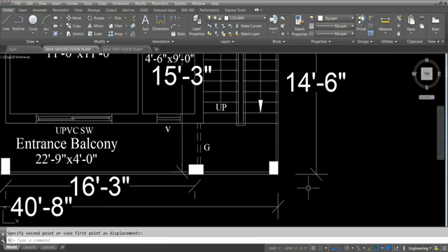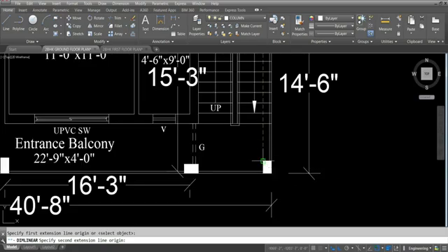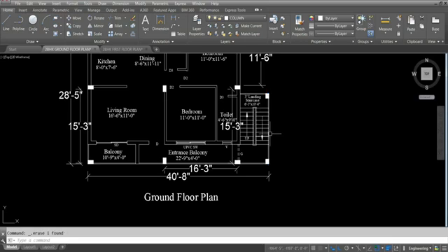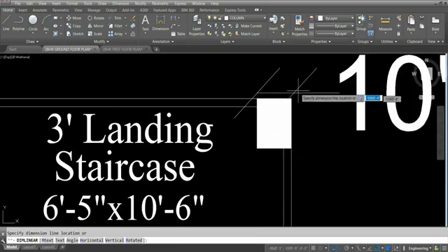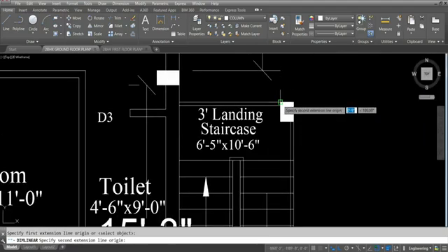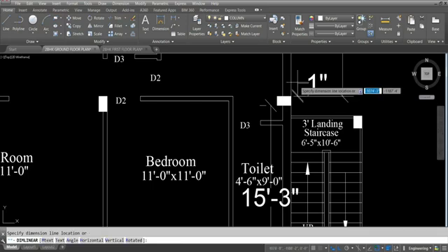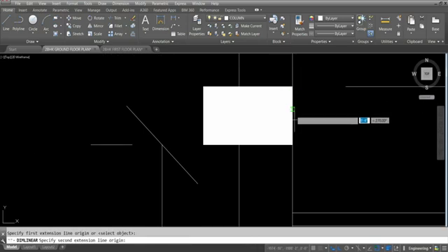Simply copy and paste. Now we can check column to column distance. You can check here. Column to column distance 12 feet 6 inch. Okay. So when it is column to column distance 12 feet or 13 feet, in that case you can take for G+3 house column size 9 inch into 9 inch by 12 inch. Okay. Sorry. This is 9 inch and this side 12 inch. Okay. But here the column size it is 1 feet 3 inch means 15 inch, and this side it is 9 inch. 9 inch by 9 inch.